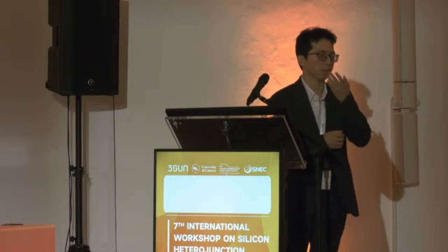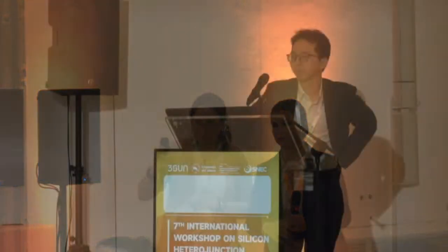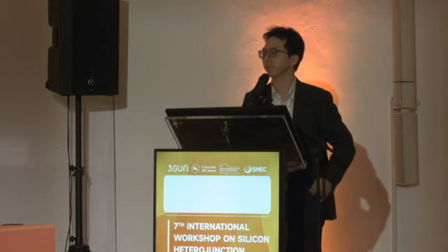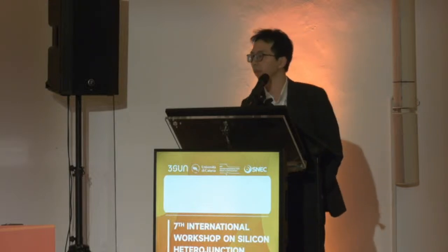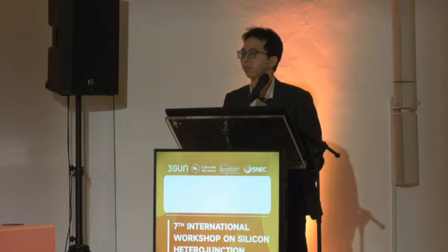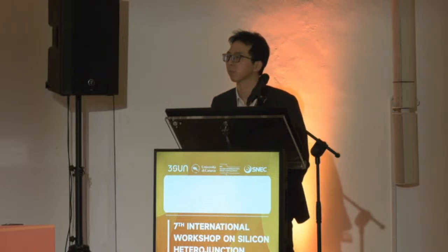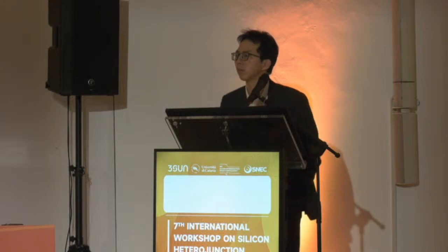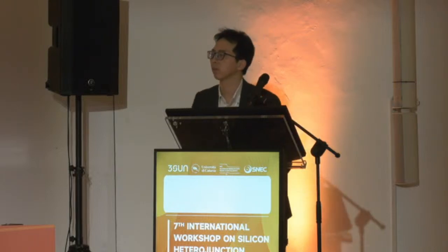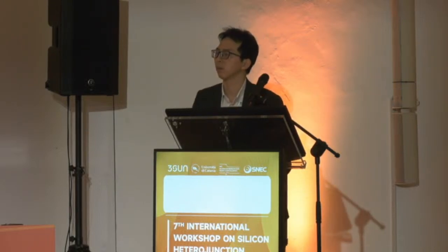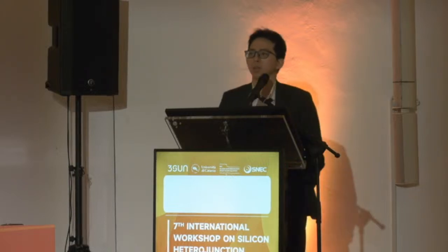Any other questions? I think we have a question there. Yeah, hi. A very nice talk. So you showed now that for the wafer thickness of 90 micron, the wafer can have a very large deformation, correct? Compared to the 150 and 130 micron wafer thickness. Okay, so my question is, in the cell production, you'll be having some vibrations. So what about the micro cracks and chipping for the reduced wafer thickness?